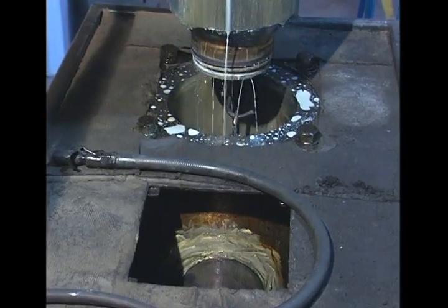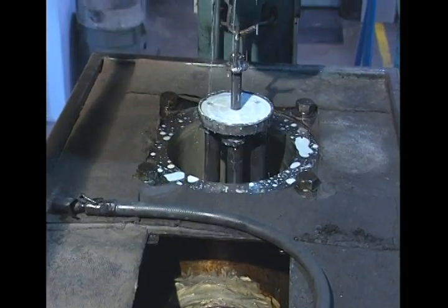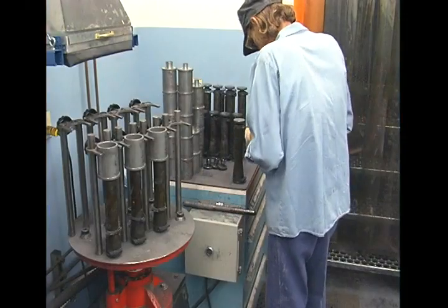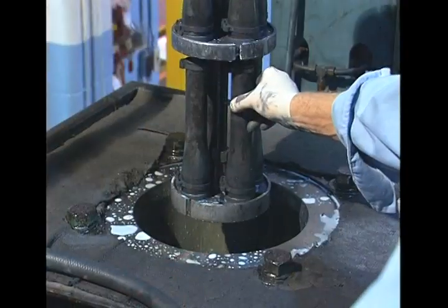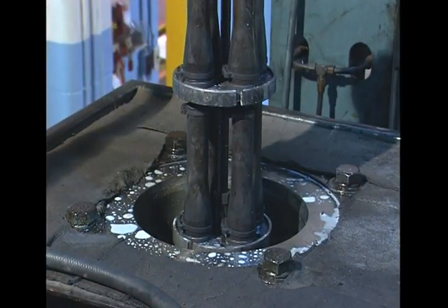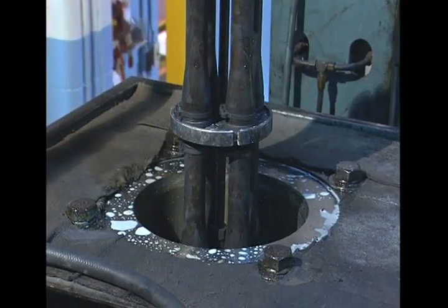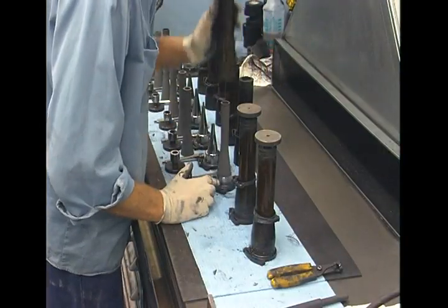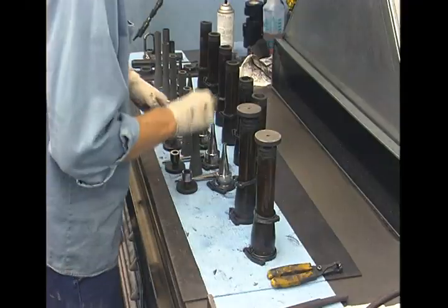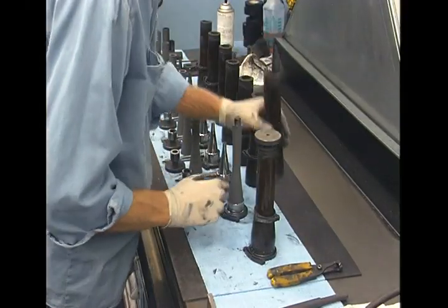The molds may be removable or fixed in the press. Removable molds are filled and sealed outside the press, then immersed in the fluid and pressurized. After consolidation and depressurization, removable molds are stripped from the part. This is called the wet bag process.